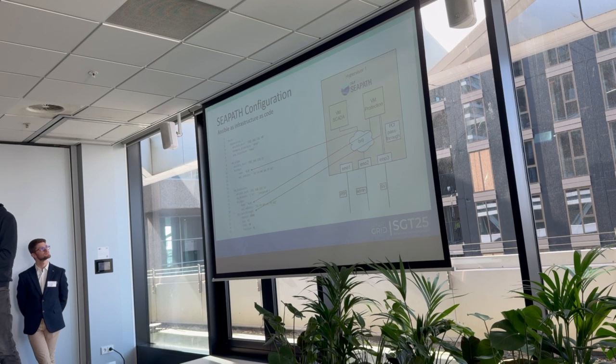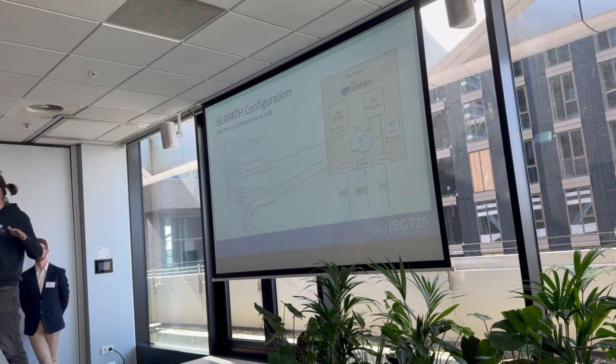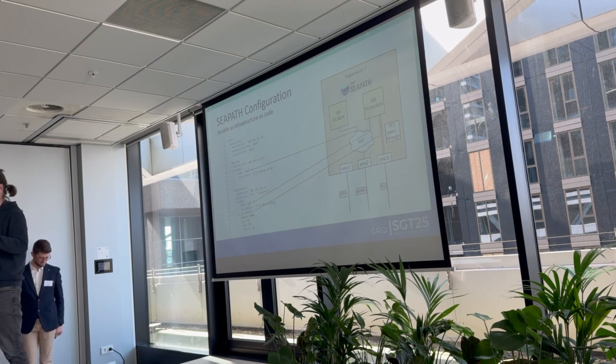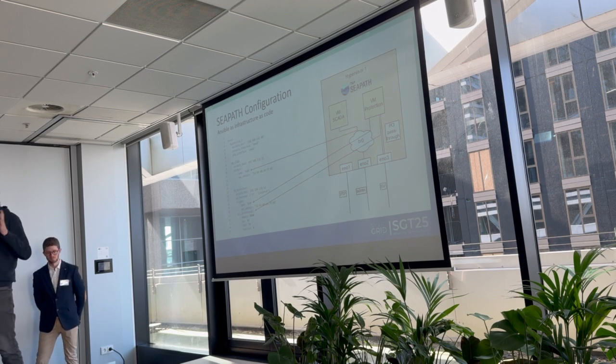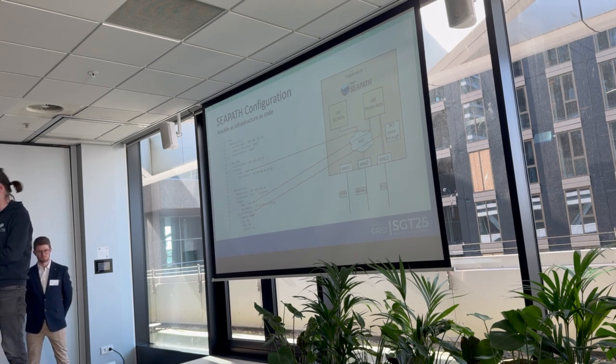Another example: the SCADA is connected to an administration bridge named BR0, and it's defined in the VM SCADA. The protection is also on the same bridge, you can see it here, but also uses a second interface using PCI pass-through. So it's basically what is described here. This is a fairly simple example, but you can have Ansible inventories using hundreds, maybe even thousands of lines of code to define your entire machines and your entire substation from a CPaaS point of view, so an infrastructure point of view.